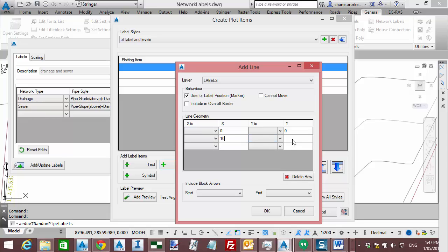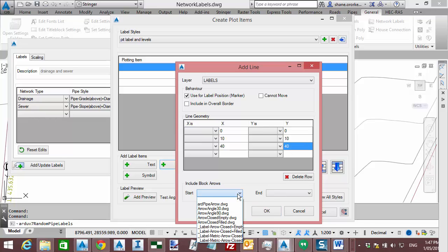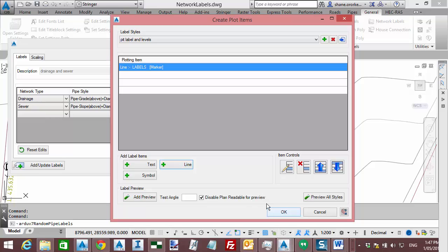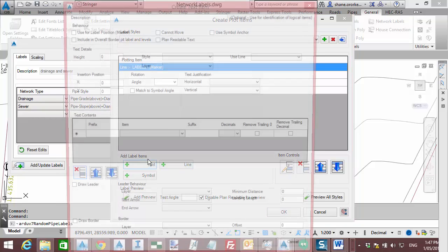For labels such as pit labels, the marker location is always set to match the pit location and can't be moved. For a surface label though, where you pick the deciding location to extract surface information from, the marker acts as that move location to pick where surface information should be extracted. Notice that we're adding 3 entries for the line. This will deliver 2 polyline segments that can be group edited separately.